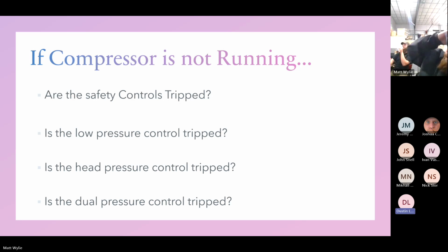I had a solenoid coil that was not working, and I told my manager I had a bad solenoid coil. And he's like, well, how do you know? And I'm like, well, I've got 120 volts to ground on both legs. And he's like, well, what do you have across it? And I didn't check. And it was 0 in this scenario. The solenoid's a load, but it's the same thing.